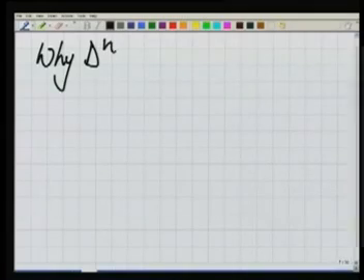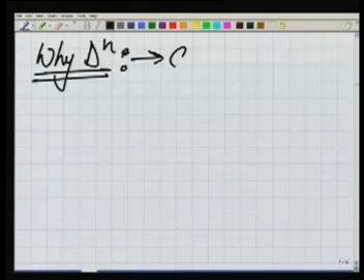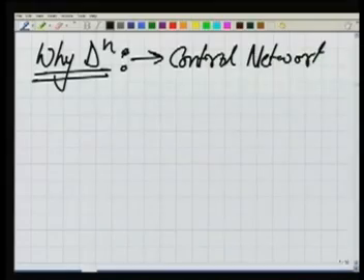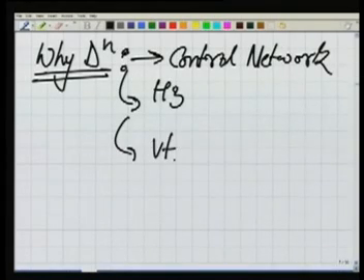Next we will go to that, because we have not yet answered why triangulation in full. By this time we know what triangulation is, how we do it also a little bit, and also the length measurement and angle measurement in that, but we do not know right now in full why we go for triangulation. The basic thing for going for triangulation is establishing the control network. Now the moment I say control, it is of 2 types. One is horizontal and the other one is a vertical control.